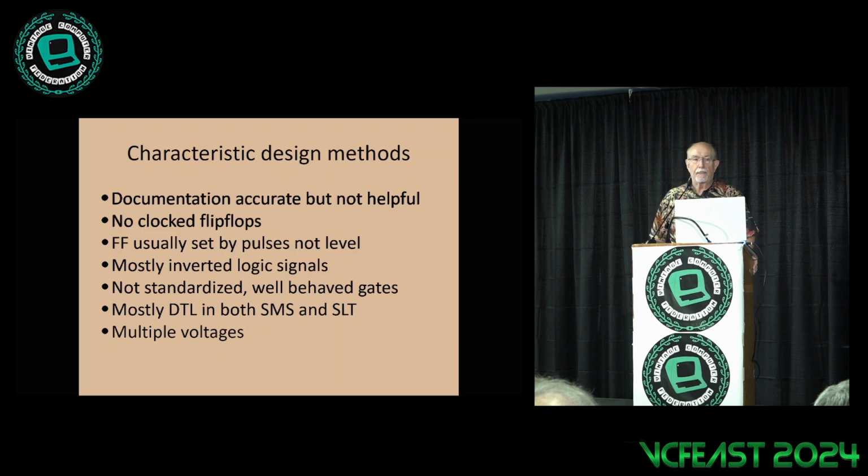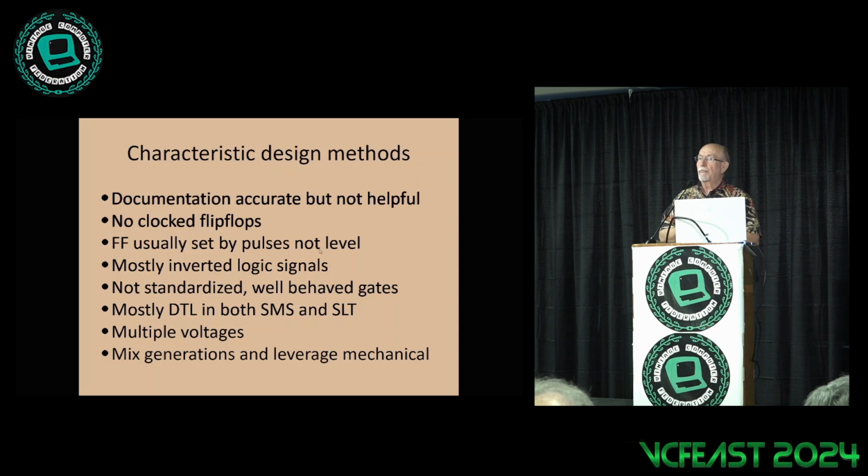Why redesign them? So you've got this oddity of power supplies that have to support equipment from the 1401 and equipment from tabulating equipment, pre-computer. And every one of those introduces another power rail. Now, even within the basic gate, each individual gate doesn't have just one rail like TTL, +5. It has +6, +3, and -3. So 3 rails just for an AND gate or an OR gate. So you're going to be dealing with a lot of power supplies when you deal with these.